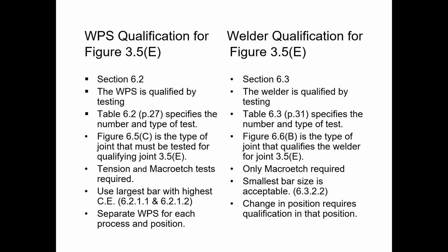You want to use the largest bar with the highest carbon equivalent. So in other words, the more stringent preheat requirement. And there's a separate WPS that you should have on file for each process and position that you're going to be performing for your embed plates or other structural components for your product.